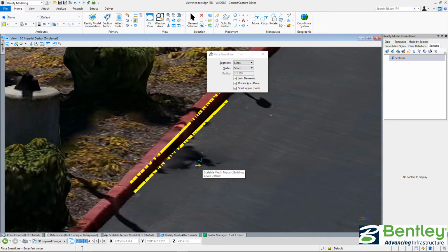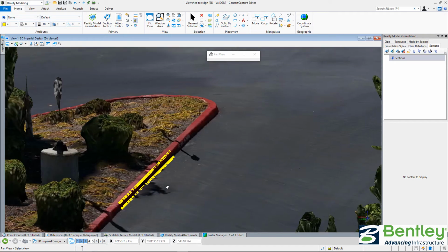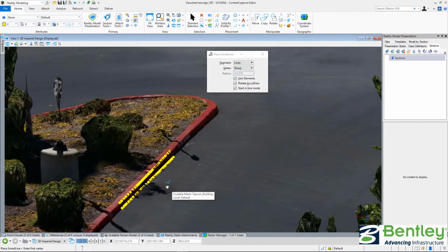As you need more detail, that's when you get a surveyor involved, where they can go out and do field survey with targets. There's actually some new tools that I heard. There's some targets that connect to each other where you could lay them out, and they will run GPS automatically where the target is, to give you that control. So if you don't have surveyors, that's another option, inexpensive. It's about $600 a target, and I think they come in sets of 10. So those are things that you can put out if you're still doing sites and you don't have access to survey. You can supplement your drone information with targets like that.